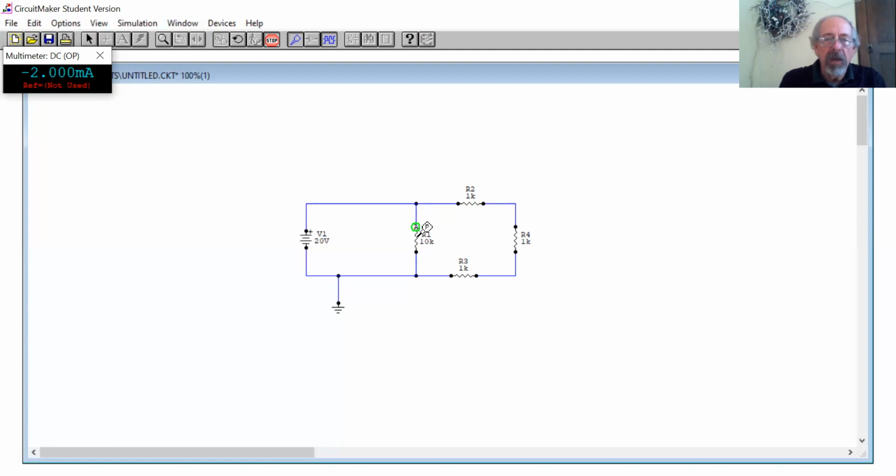which is still the 2 milliamps. And I didn't mention power. The probe goes to a P and actually tells me I've got 40 milliwatts of power in that resistor. Or if I go over to the battery, it tells me I've got 173.3 milliwatts going to all these resistors here. And each resistor over here, what do we have? 44.44 milliwatts. Again, all kinds of calculations are done automatically for you. You don't have to do all the paperwork. That's kind of nice. Okay, so that's DC.